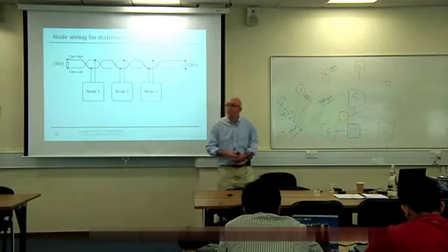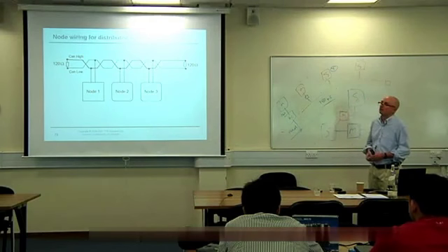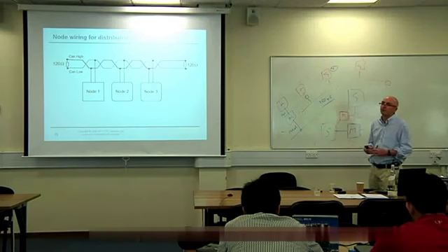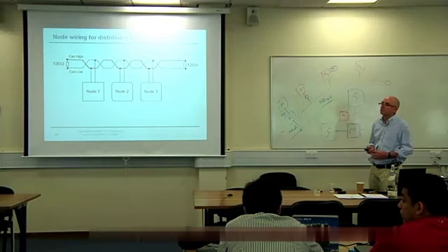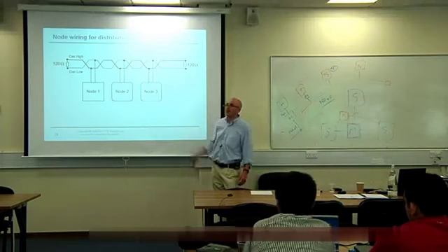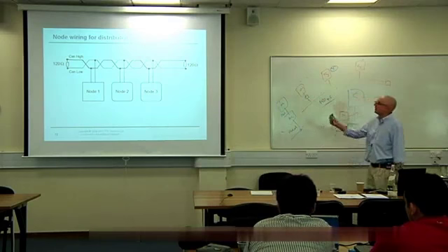It's differential signaling. What does that mean? Well, the signal is considered as a difference. So why is that good? You can get more meaning over the two things. If there's any signal, like radiation or whatever, in the cables, it's on both of them, so it cancels out. So if electromagnetic interference adds a 10-volt blip on here, the difference will remain the same. So it's essentially pretty robust.